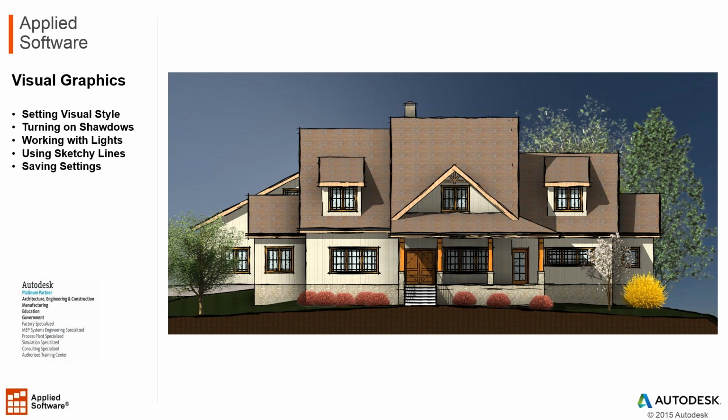So every time that we make an elevation, it instantly looks like this, and we don't have to have any adjustments done to it. So we can pre-configure that in our template file so that when we do start a project, it is set up initially just like we like it. So again, very powerful. And none of this is renderings. I didn't even touch the renderings here. We could take a view and actually render it and create a rendered image, but this is just turning on colors and shadows is all this is. And so there's no wait time for this as far as waiting for it to render or anything like that. You can create some pretty nice views without having to create a rendering in there.